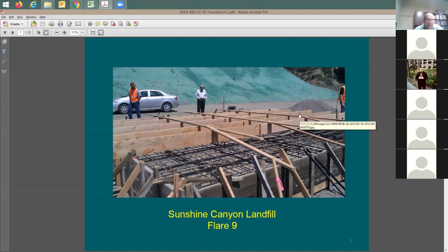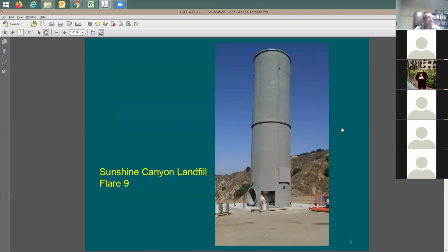Yes. So for this tributary area, if I give you dead load and live load and say that you have a 7-story building or 6-story building plus a roof, and they give you an elevation, you can count the number of floors, right? Multiply by tributary area, multiply by dead load and live load, and also the roof. You need to consider the roof, combine it, and of course use 1.4 dead versus 1.2 dead plus 1.6 live, correct? So okay.